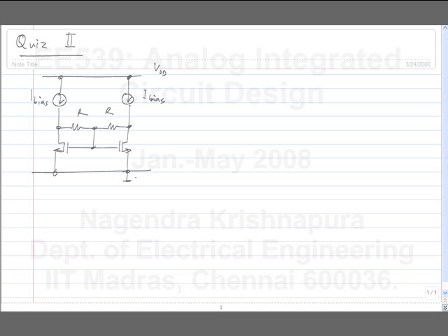This was the problem. From the schematic, it's pretty obvious that it's symmetrical, with the same excitation to either side. So it is like the common mode picture. Even if you don't recognize that, you can easily calculate the answer by thinking of it as an independent circuit. If we do use symmetry, this voltage has to be equal to this, and that's all there is to it.